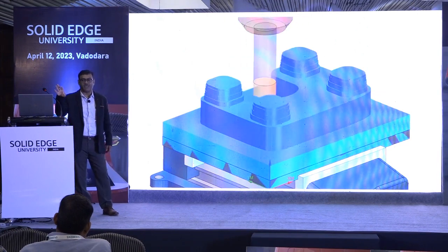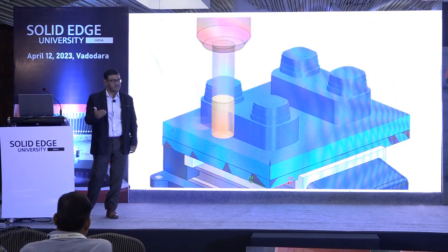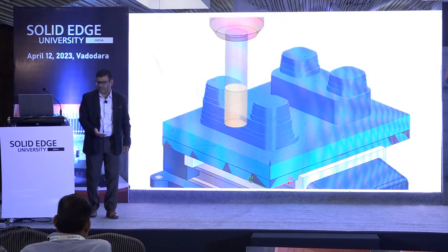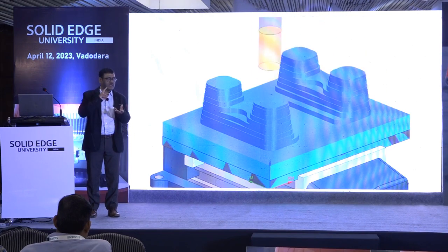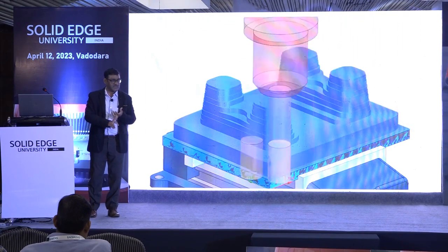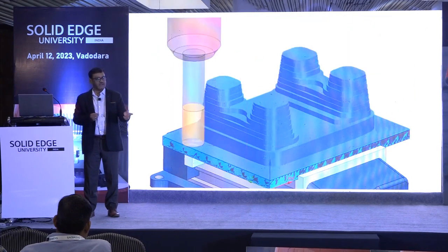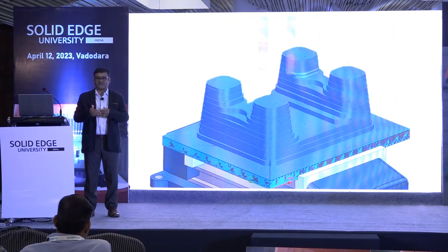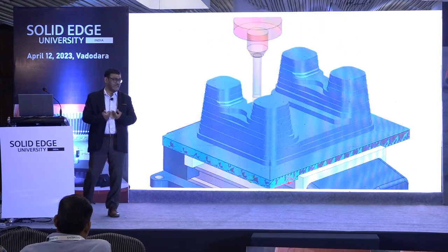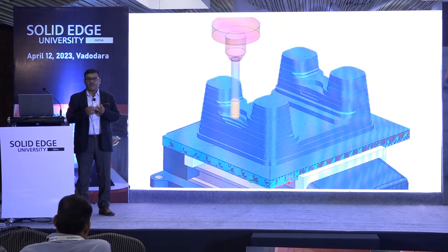This is one of the ways where you create the toolpath and create an IPW, what we call the in-process workpiece, in a Solid Edge CAM Pro environment. Check whether it is satisfying your machine need, your operator need, your futuristic need, anything and everything, and then modify virtually. Check that, and if you are fine, only then load that program to your machine. Otherwise, you can optimize digitally. That's what we call the digital twin of the product and the production, right? So you can validate the program.